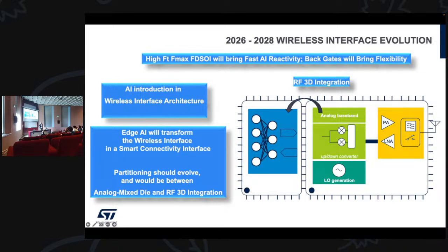So not one multiplication, but numerous multiplications with a step of the reference frequency. So it means you have a 2 gigahertz. If you want to do between 110 and 130 gigahertz bands LOs, you have one LO at 110, one at 112, and so on and so on. So this is a possible solution.